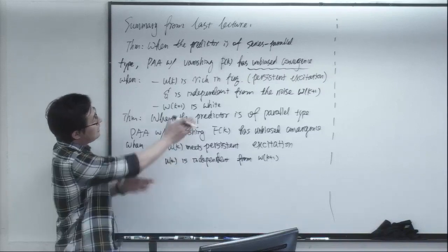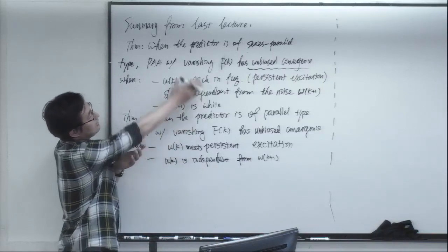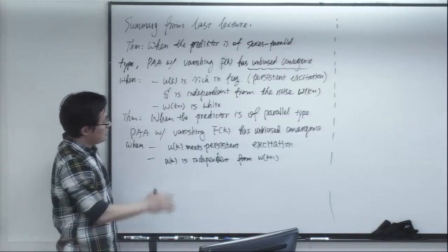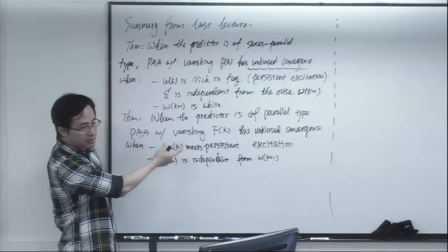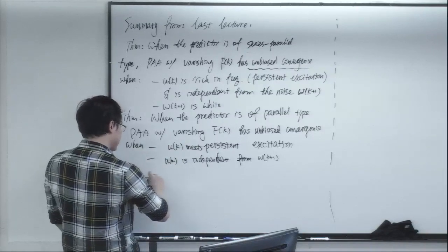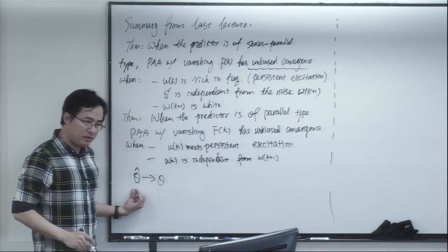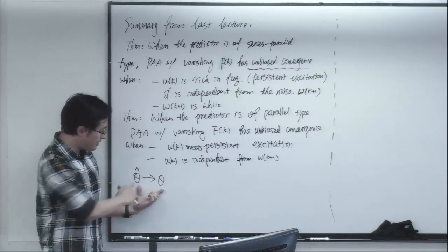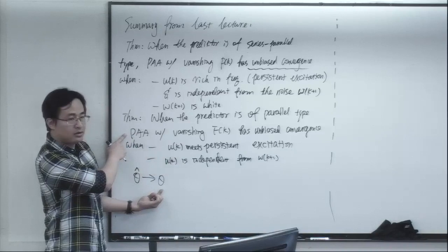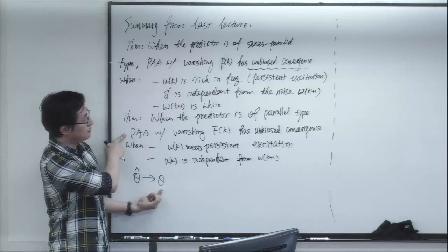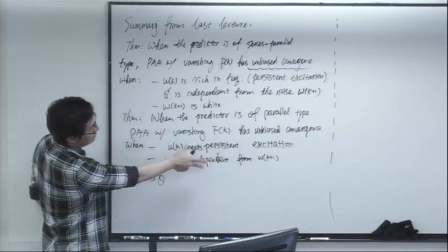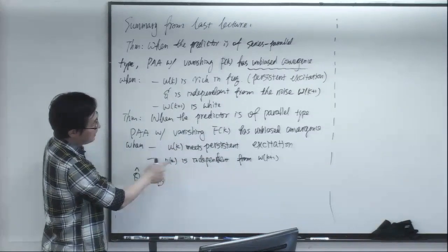Usually, we can't expect the white noise in the series parallel structure from the block diagram that we drew. So, in practice, if we focus on having really good parameter convergence, we want theta hat to converge to theta, then this parallel structure is usually the preferred method because it has easier conditions for unbiased convergence.